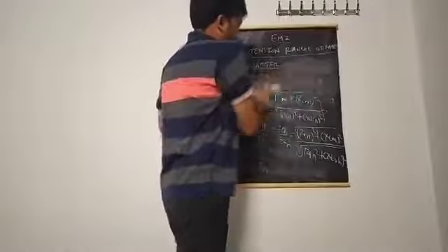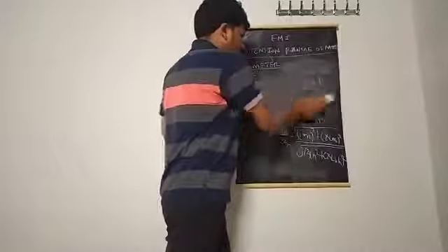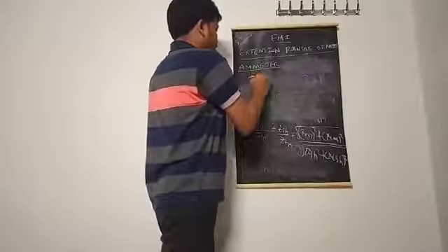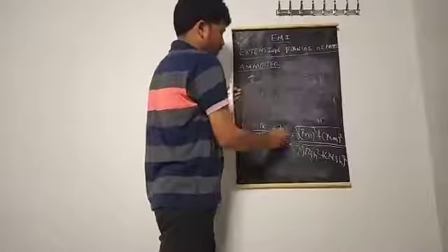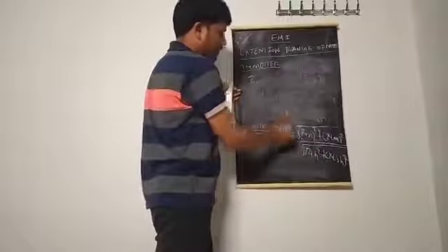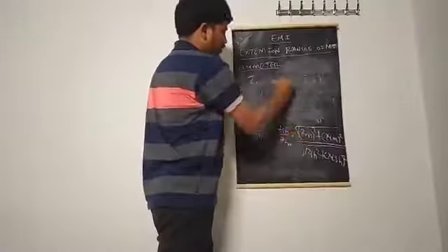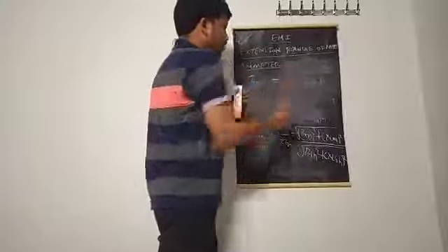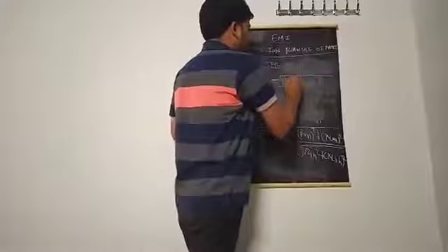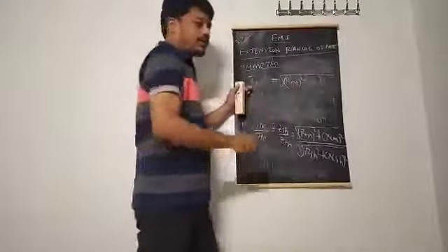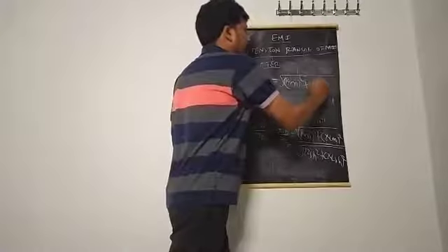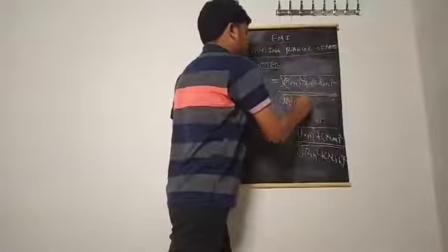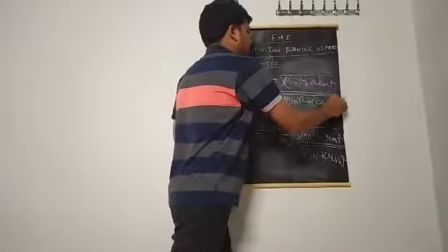So, after substituting here, from this equation substitute XLM and XSH here. I am writing the right side equation. Every time the left side is not needed, we will write it at the end. Okay, then square root of Rm square plus XLM, which is nothing but omega Lm, whole square by square root of RSH square plus omega LSH whole square.